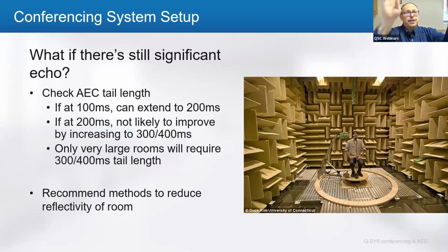The speakers 10 feet away from me maybe get 6 dB down of my signal, and the speakers 15 feet away from me on a separate speaker zone would get it 3 dB down from my signal. There are some creative ways I've seen people do this. If the loudspeakers in the room are primarily being used just for conferencing or voice lift, and you only have one amplifier channel, you can tap the ones at the front down a little bit more and tap the ones at the back of the room up. But now we're getting into hypotheticals and not preferred case scenarios.